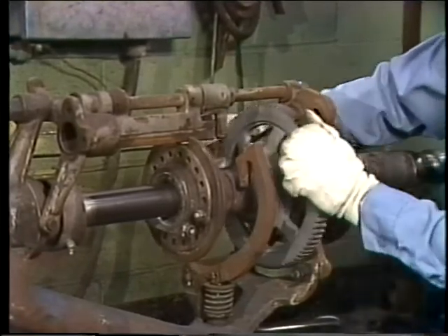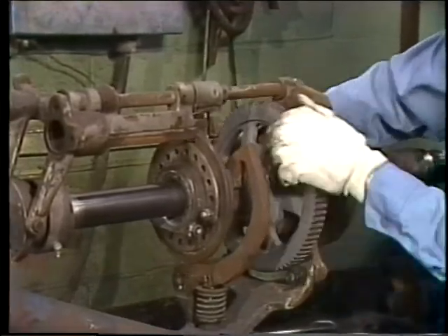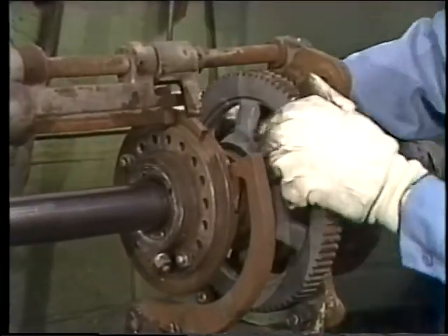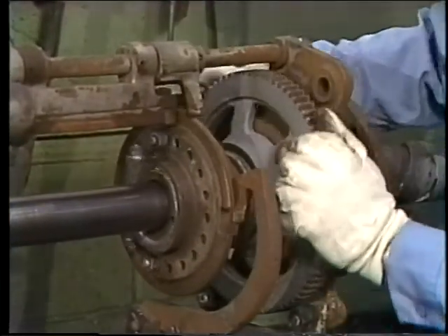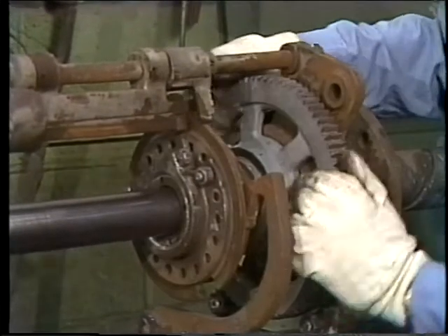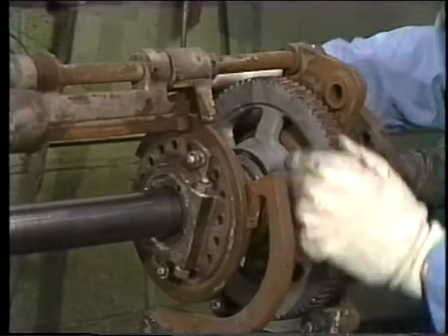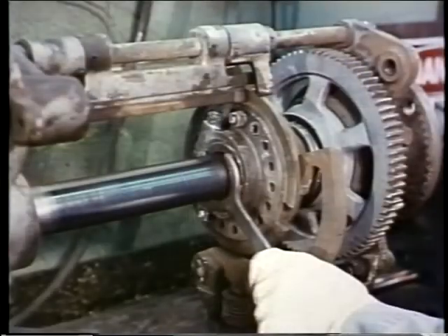Now's the time to manually run the soot blower through a complete cycle. This will make sure that the cam catches the trigger properly, and when it's driven back, that the trigger is released from the cam and the element drives smoothly back in. At this point, the tube packing can be tightened.